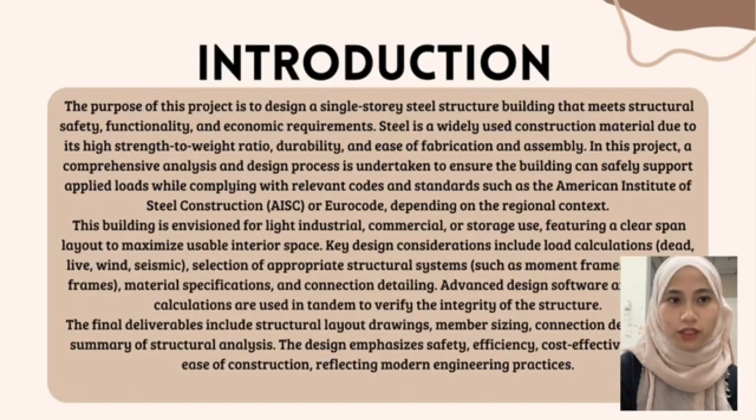Key design considerations include load calculation, dead, live, wind, seismic, selection of appropriate structural systems such as moment frames or braced frames, material specification and connection detailing. Advanced design software and manual calculation are used in tandem to verify the integrity of the structure.